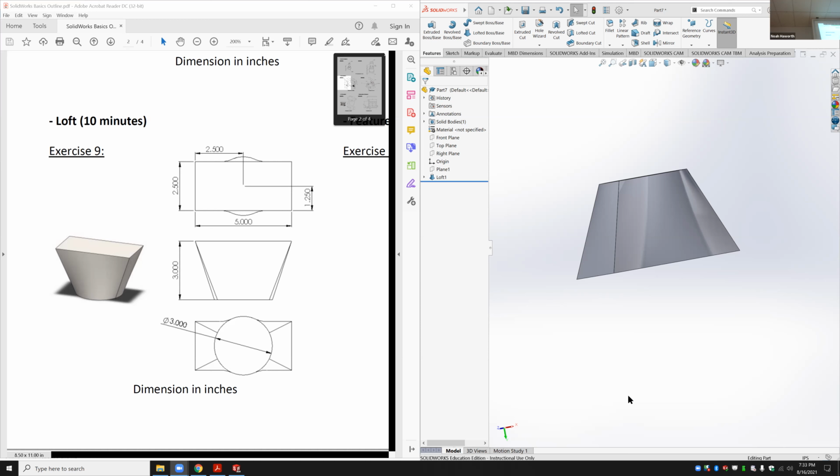So go ahead, drop down over here, the little arrow. Sketch. Yeah, you do want that one. So edit that. Right here. There you go. What you want to do is draw a line from this corner to that corner. You're still in the line command, so go ahead and close that. Or actually, sorry, take it back. Change it to construction. Now you can close it.